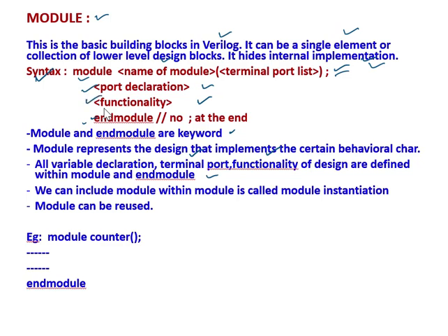And we can include a module within a module, which is called module instantiation. For example, inside this module and endmodule I can have many modules. If I want to import other modules for my design, I can do that, and a module inside a module is called module instantiation.